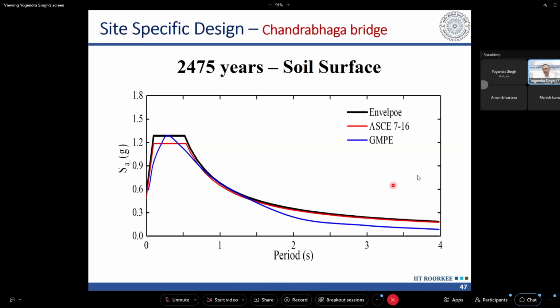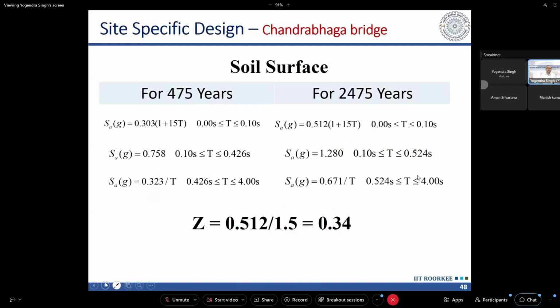And the reason for this is, as I explained earlier, that MC is higher amplitude motion. So with higher amplitude motion, the energy dissipation in the soil is more. So amplification in MC is different than the amplification in DV. So this is another important aspect which is currently being missed in our course.